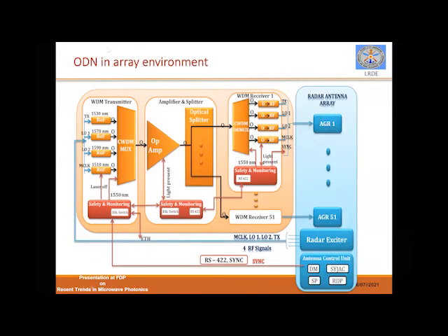Now the scheme which I showed you, scheme 2, you can see that this is the radar exciter. This is a hypothetical situation where we want to transmit 4 RF signals and 1 sync signal. All the signals which are coming are converted to the optical domain. These RF or analog signals are converted to the optical domain by using RF transmitters. So one is a yellow signal, this is another yellow signal, this is the clock signal, this is the transmit signal.